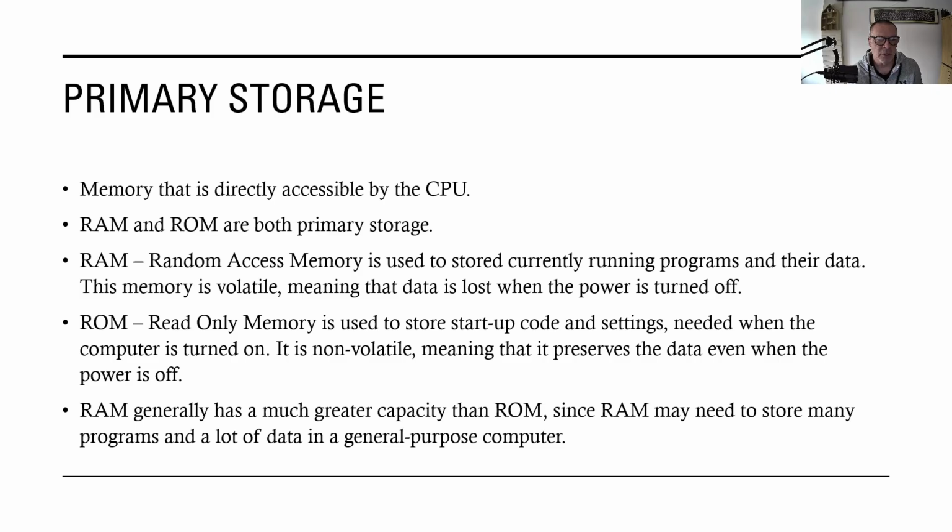ROM is read-only memory. Originally read-only memory was read-only, you can only read it, but now it's a bit of a strange name because there are ROM that you can write to, but we'll come on to look at that later. But ROM is used for startup code and settings, the stuff you need when you first turn the computer back on again after it hasn't had power. So when it first gets power, you need to find somewhere for instructions and data. You can't use RAM because that's lost everything. You need to use something that's non-volatile, and that's usually ROM.